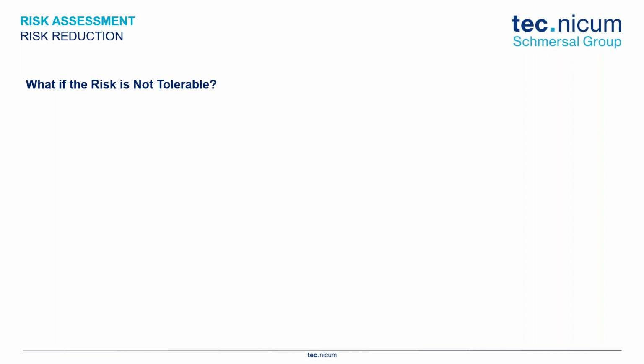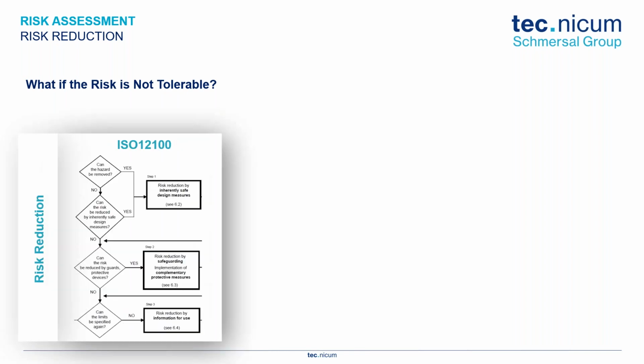We document it, we move on to the next hazard or the next machine. But if it's not acceptable, if this hazard and risk is not acceptable, we then move further down on that figure. Again, the figure that I showed earlier for the risk assessment, just one part on one page. Here are some of the other parts on that same page where we're saying, okay, this risk is not acceptable. We then try to see what can we do to eliminate or reduce these risks.